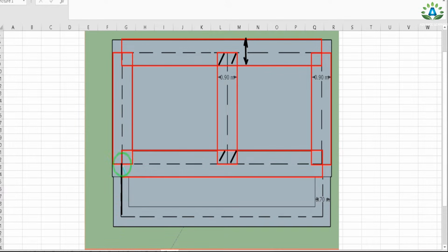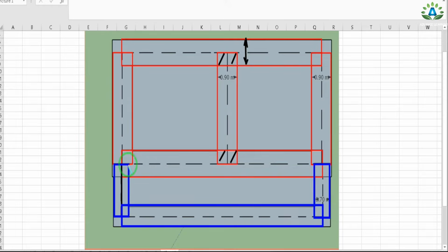So when we multiply this center line by the width, that is 0.7, then we will get the areas. And here we can clearly see that this portion is considered twice. That means while calculating the area from this side as well as from this side, this portion should be subtracted. And here also we can see that this portion is also considered twice. So we have to subtract this, having the width of 0.9 by 2. Here also 0.9 by 2.